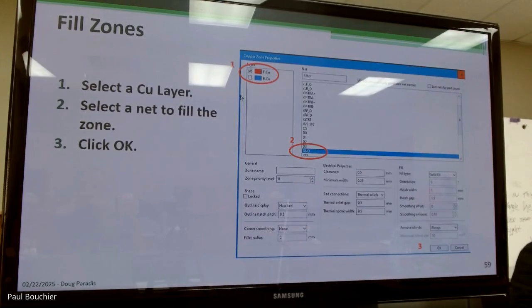If you want to unfill it, you use Control V, and that will unfill it. Now, you say, well, why, Doug, would I want to do that? Well, you might want to do that because you found you needed to make an adjustment to the board. Because the fill area will, every time you hit V, recalculate and adjust for whatever you've done. It is nice because when you unfill it, you can move the corners, you can move the edges. Oh, you can? Yeah, you can move the edges.